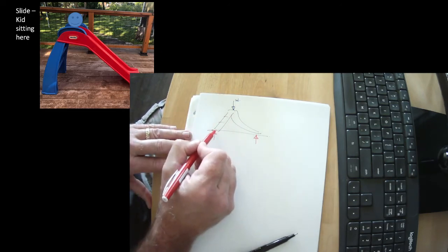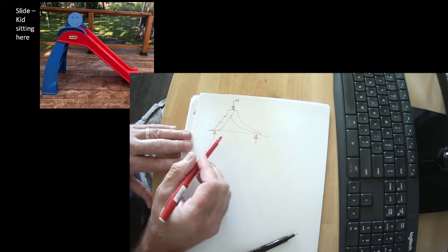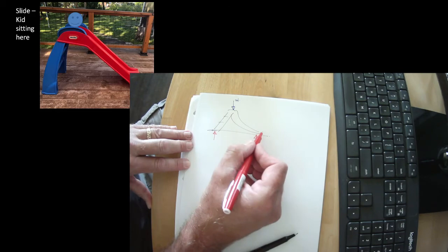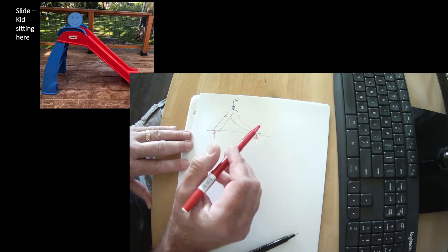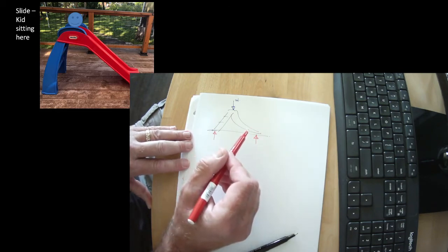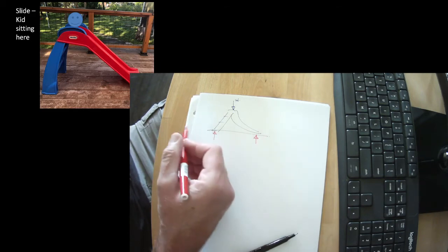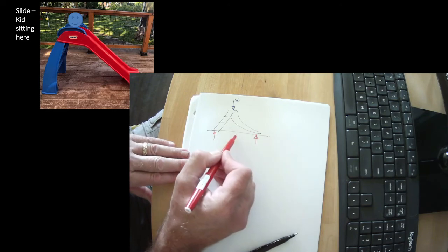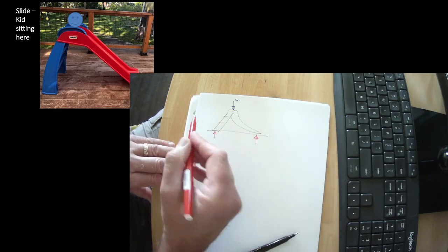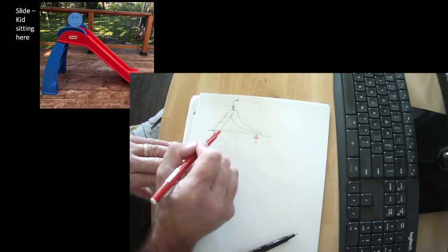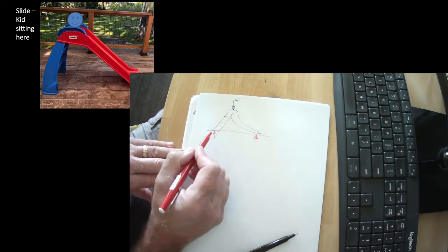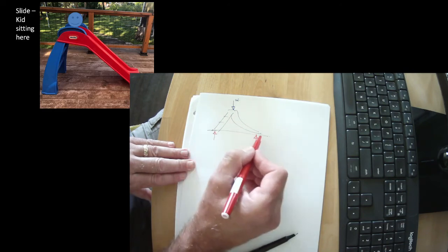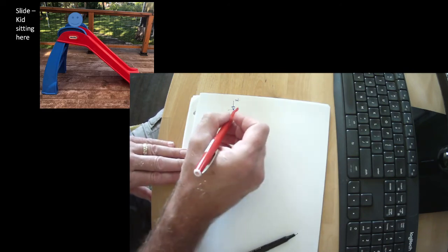This is one of those ones, though, where the slide looks kind of like an arch, right? But we have to consider the surface to be frictionless, and the slide is virtually weightless. The slide doesn't weigh anything. So this can't work like an arch. It has to work like a beam. The structural behavior of this, notwithstanding the triangle, is a beam.